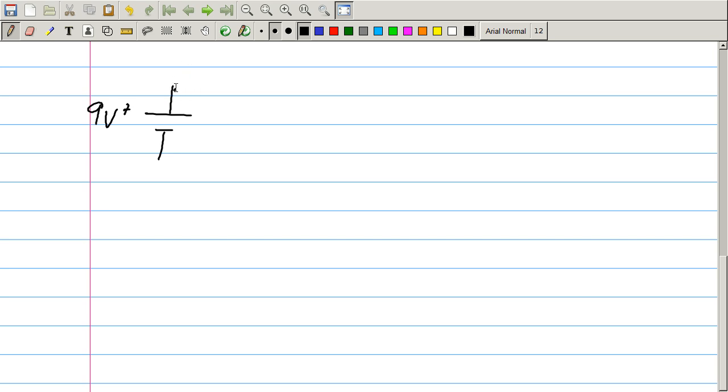What you can do is connect that to the non-inverting input of the comparator, and then connect the inverting input to a voltage divider. That's a potentiometer, very poorly drawn. Let's see if I can do that a little better. Connect this to a potentiometer. I guess that's as good as I'm going to get.